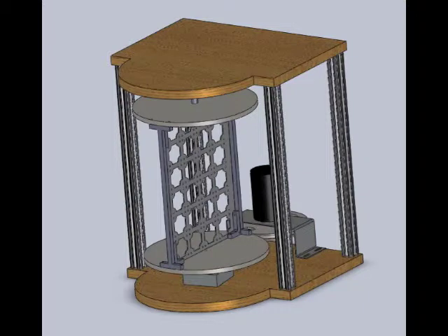This assembly will be spun at 1500 RPM on the lathe, and accelerometers will be attached to the lathe in order to measure the vibrations caused. As a control, the lathe will be spun at 1500 RPM without the proposed assembly, and data will be taken. We will then look at the difference between the two measurements. If the vibrations are substantial, research will be made to see if counterweights can be installed to improve balancing. If this is too difficult to accomplish, we will look into design alternatives.